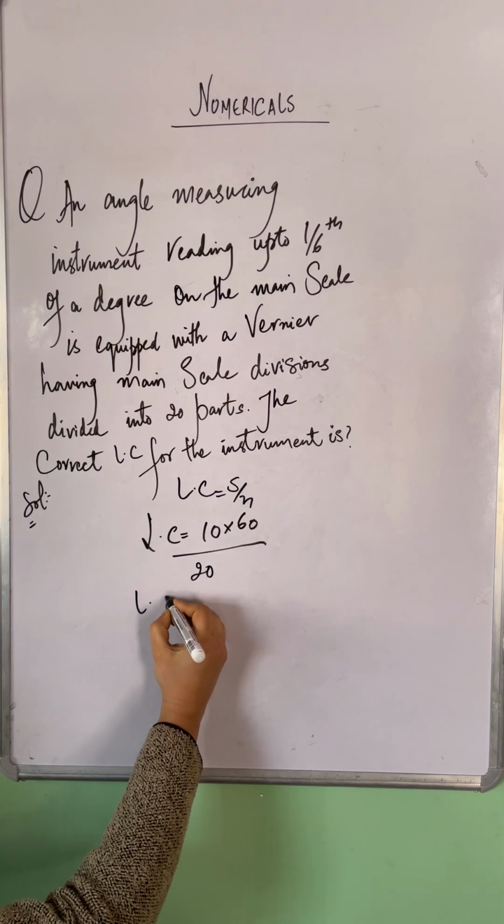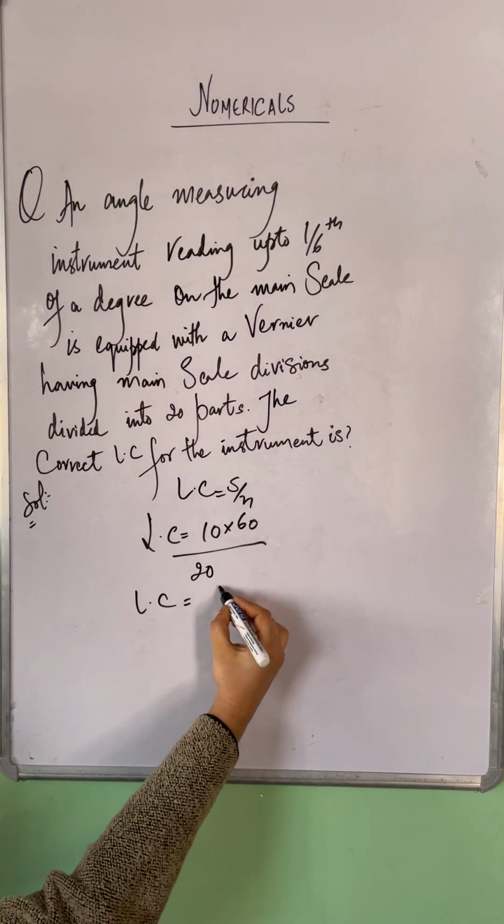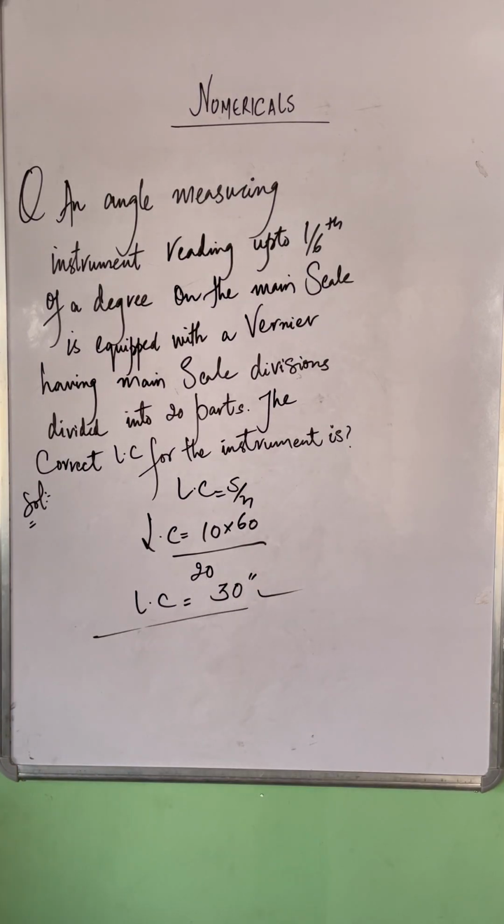So the least count for this instrument comes out equivalent to 30 seconds. Right? My least count is equal to 30 seconds. All right, let's do another question. We're trying to solve as many questions as possible.